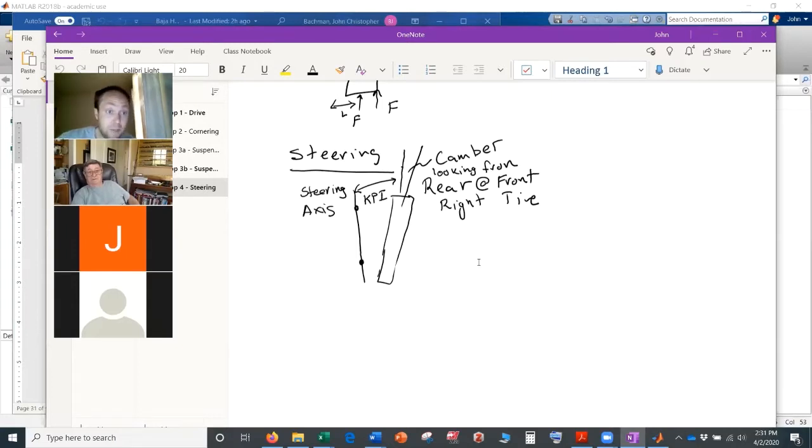So you typically want a little bit of kingpin inclination. So you want your KPI, I don't know, books say in the 5 to 10 degree range. And what that basically does is you imagine when your tire needs to turn, it needs to dig into the ground, right? For your tire to basically turn. So imagine pulling this tire towards you, because that kingpin angle is kind of angled to the left, it digs it into the ground. So that helps you give some stability in your steering, right? So this provides stability.